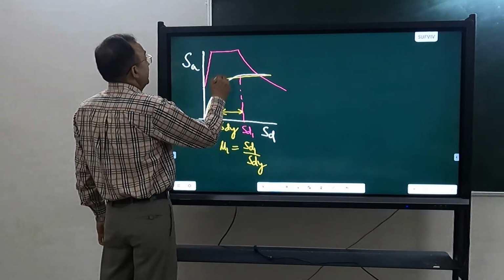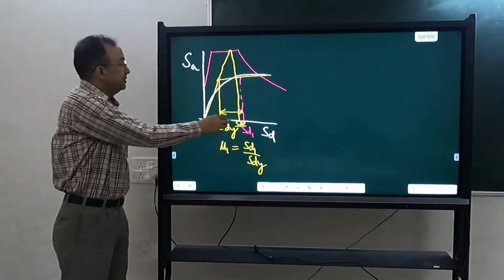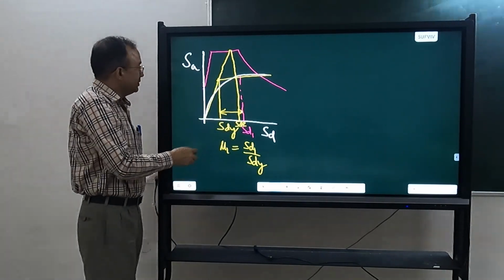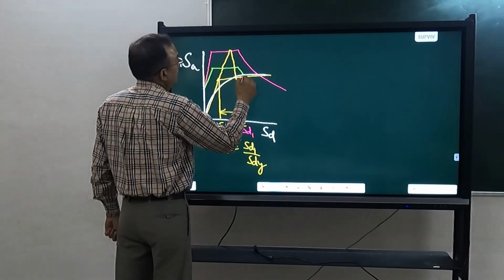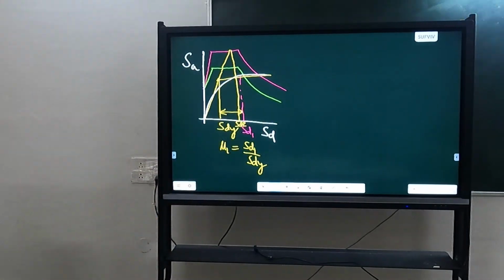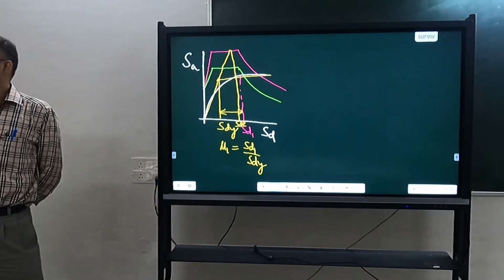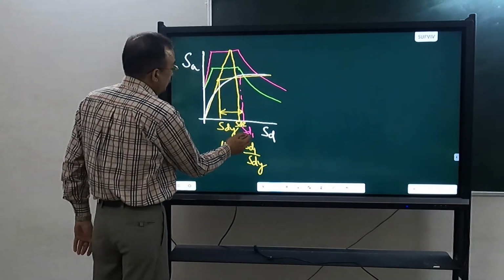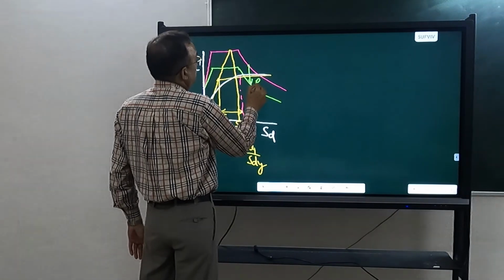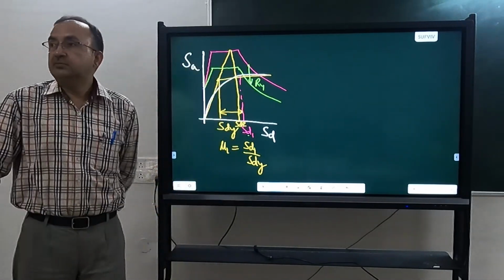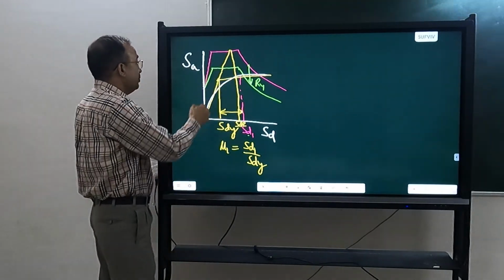The displacement I can calculate. The elastic displacement will be this. So I will assume this SD and SD1 are very close. I know the mu. Now for this mu, I can calculate Ry and I can reduce this response spectrum like this. Then I will calculate the displacement corresponding to this reduced spectrum. And if that displacement comes out close to this, you have to keep in mind that this is reduced by Ry, but the period is the initial period only. So you have to calculate displacement corresponding to the initial period only.